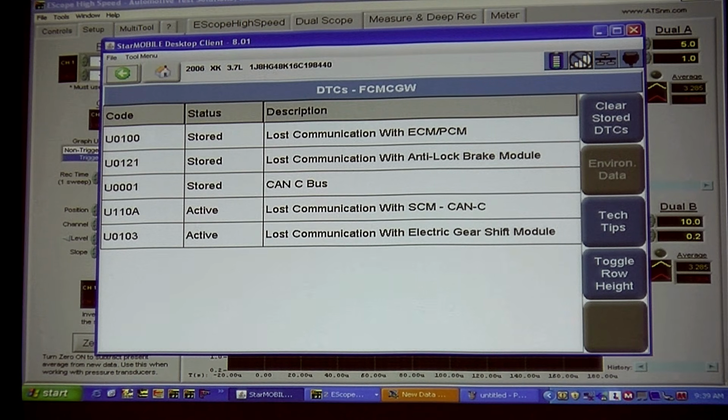Remember how we looked at this. Remember how it works. We go through arbitration, we set the RTR bit, everything in front of that is not checked. After RTR, we check it with a cyclic redundancy check, and then we destroy the frame or we allow the frame to be. If we destroy the frame, every time we destroy a frame, that's 8 points. Then I've got to have 8 good transmissions to delete those 8 points. Do you start to see? So this is how we're going to get codes. We're going to set codes at somewhere 90 to 100 counts.